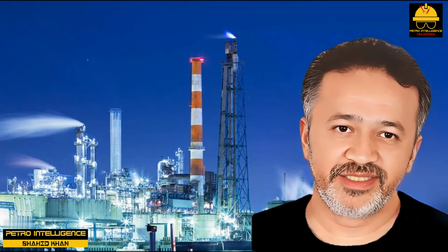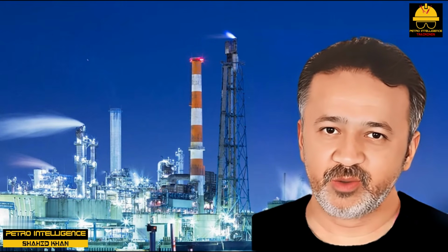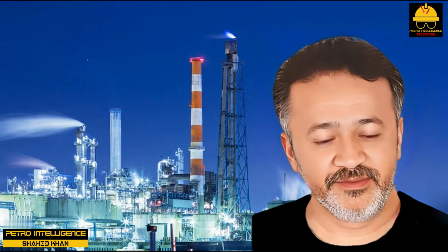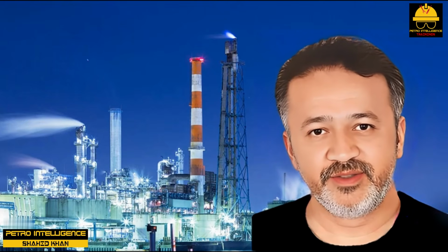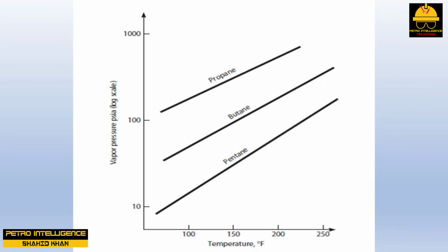Many of the tubes in the condenser would be submerged in the liquid refrigerant. The refrigerant would be subcooled below its condensation or bubble point temperature. It would have to be subcooled so that after the liquid lost 10 psi of pressure it would not flash. To subcool isobutane so as to prevent it from vaporizing after losing 10 psi, the isobutane vapor pressure must be reduced by 10 psi. This would, in turn, require cooling the isobutane by about 5 degrees Fahrenheit.